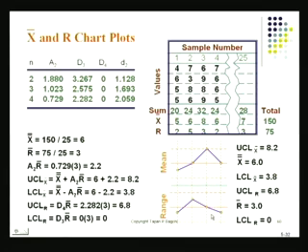To remind you again, we need both the mean chart, which is the X bar chart, and the range chart, because we are concerned about 2 aspects of the process. One is accuracy, the other is precision. Both of these have to be checked, certainly when the data quality is measurable. I need to know if the process is producing items which have their values pretty close to the target value, and this is an indication of accuracy.